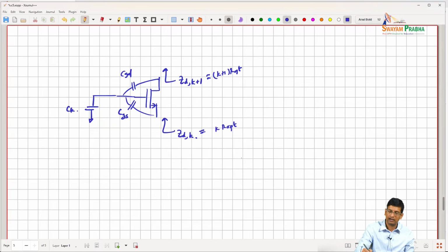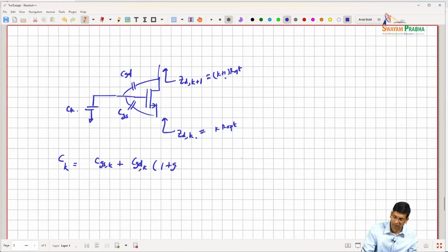So I can write an equation to make sure that, assuming the real part of the impedance looking up is K plus 1 R opt, what do I need to do to make this one K R opt, right? So that ends up depending on C K, and you can come up with a design equation that serves as a good starting point in the design.